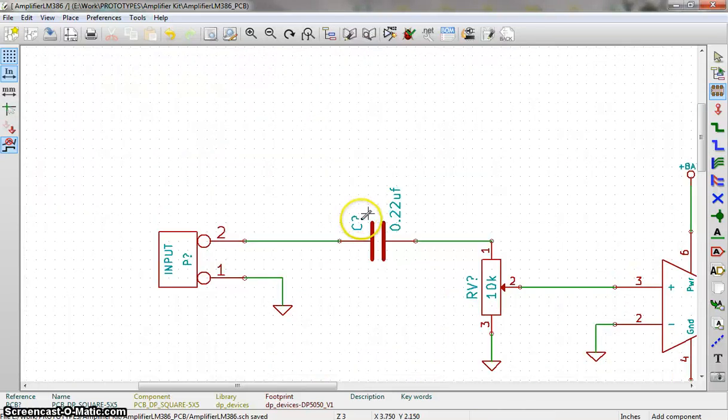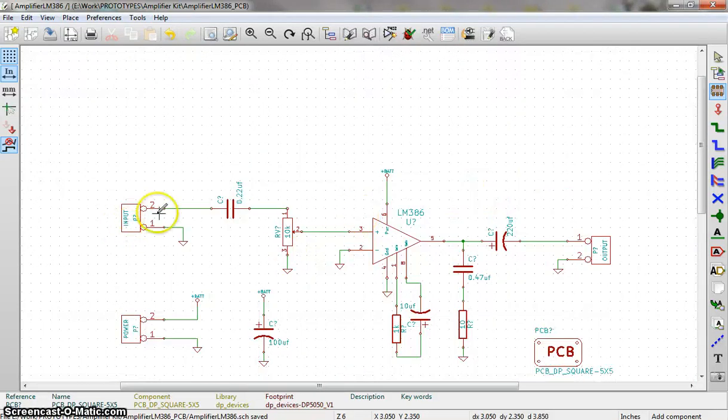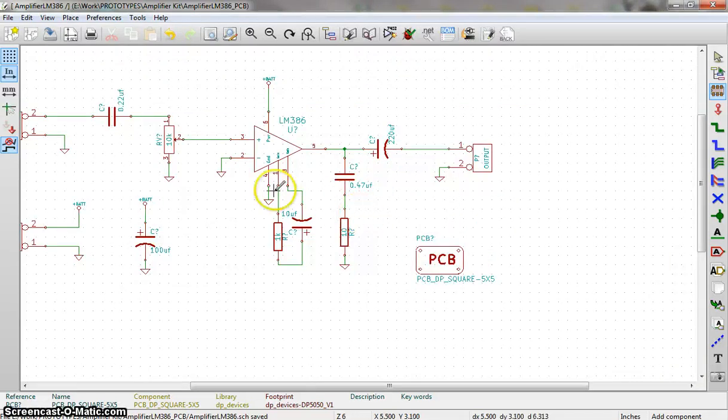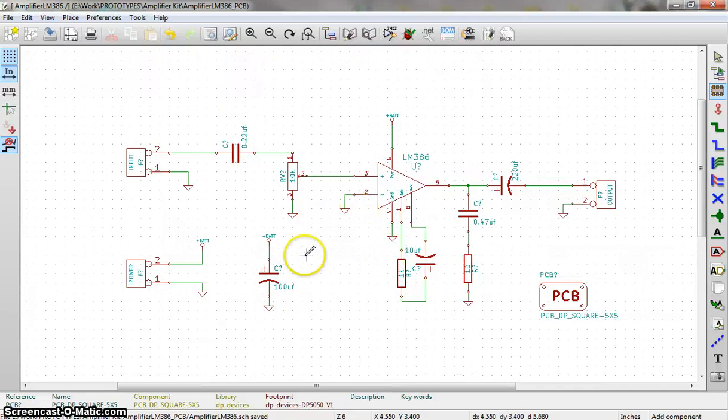So now we have everything that I think we need on my schematic, but you can see there's a question mark over all of these references. That's because it hasn't been what's called annotated. So it says this is number P1, this is P2, this is G1. Generally, you need to do an annotation before you can do anything else, or else it doesn't know what everything's called.